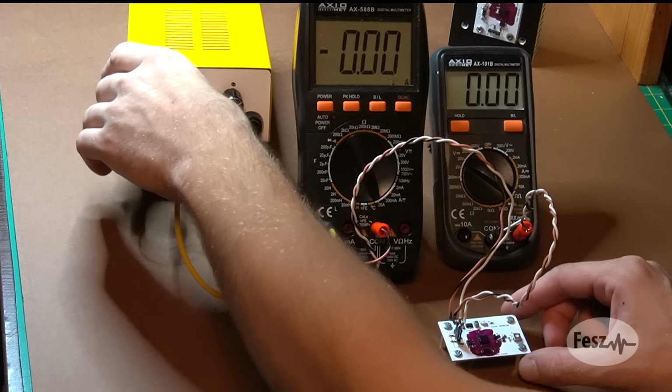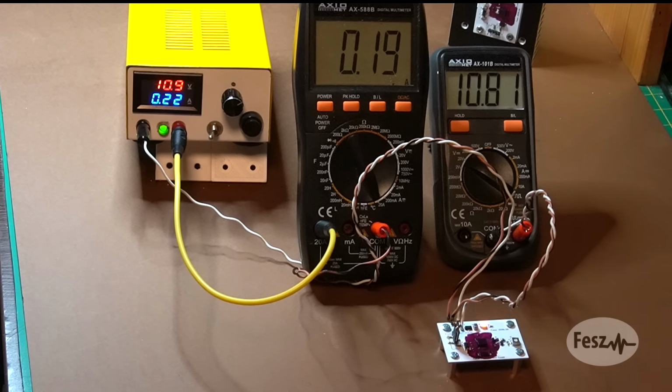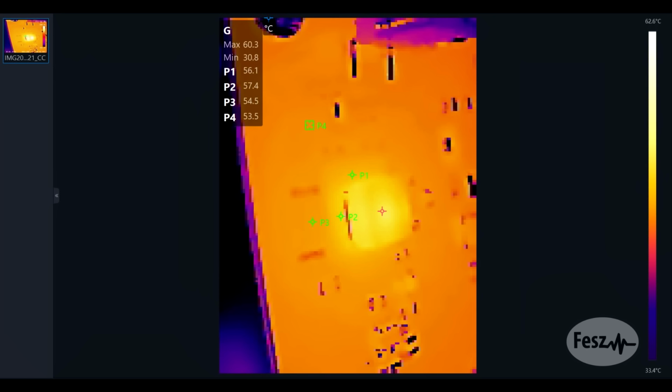For the board without a heatsink, I set a lower 2 watts of power dissipation, just to prevent any accidental overheating. Here again, we can see a similar story. The aluminum substrate does provide a good temperature uniformization, so other than the transistor hotspot, there's no gradient really visible. When zooming in, we see a similar heat spread coming from the transistor. The immediate area is hotter, but then it just reaches the same temperature as the rest of the board. So, based on the temperature difference and the power dissipation, we're in the similar 1 to 2 Kelvin per watt range.